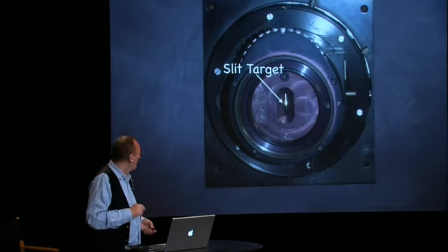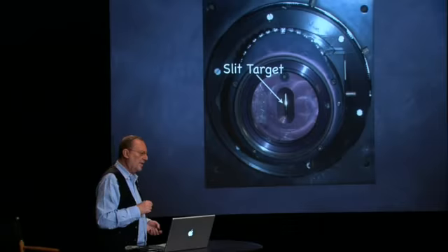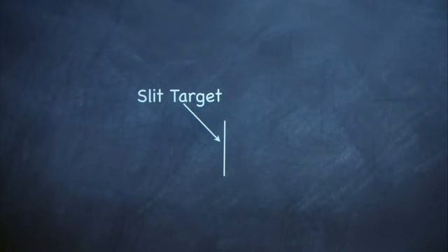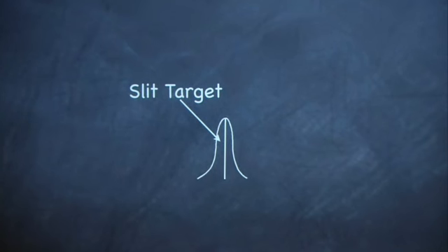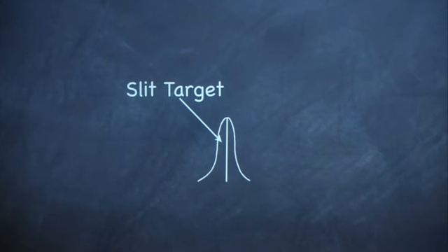Here we go. That's what the lens is looking at, and it is imaged onto a line array CCD. If you remove that, that would be an ideal representation, an impulse response of that slit target. In reality, we end up with a spread function that looks something like this. That line spread function, through a mathematical transformation that happens in that computer back there, will give you an MTF curve.